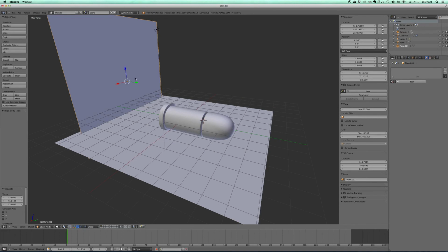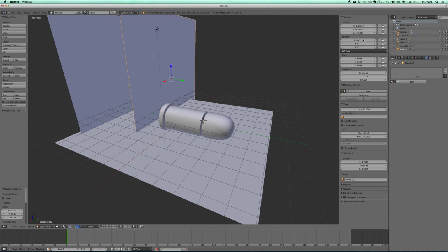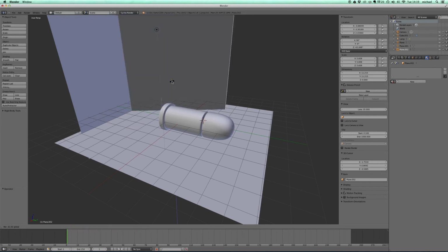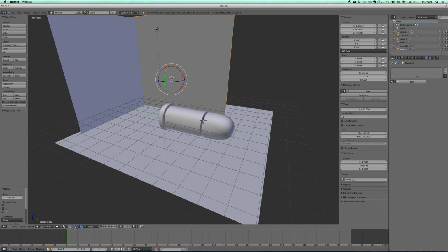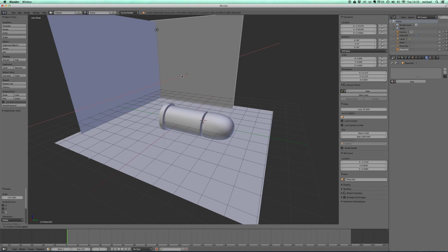And now what I want to do is I'm going to duplicate that, Shift D to duplicate it, and then this one I am going to, Control Z. I'm going to rotate this one in Z, and I'm going to make that, let's say, 90 as well. So now what I have is a tiny little scene. It's not terribly exciting, but it does work in terms of there are two walls and a floor.